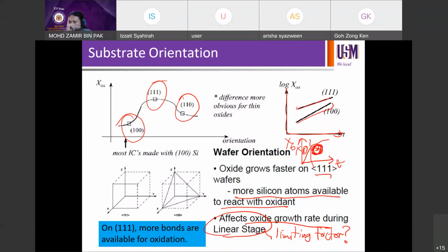So the transport of oxidant, or the diffusivity of oxidant through silicon dioxide to reach the silicon on the other side. We already have a barrier at that time, especially if the barrier is already thick and growing thicker, it's going to slow down even more, because the diffusivity of the oxidants will be the limiting factor in the second stage.